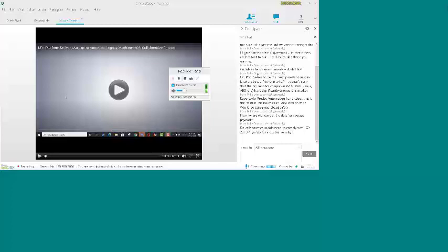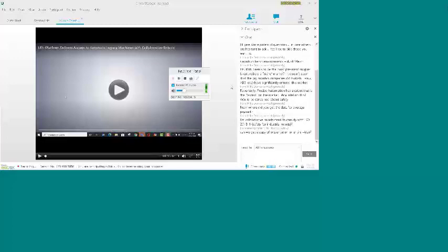All right, so a question: cobots in harsh environments, heat or dust. So yes, the cobots are rated for IP54 settings. They also have sleeves you can wrap around the robot arms to make them more suitable for a hotter environment, or say a spray paint environment where there's spray paint particulate matter in the air. So they do have some potential options to help them adapt for harsher environments.